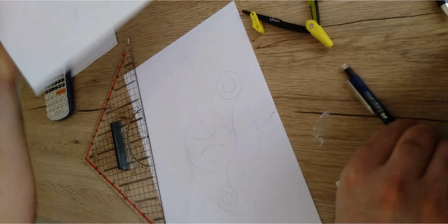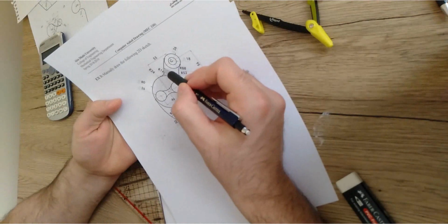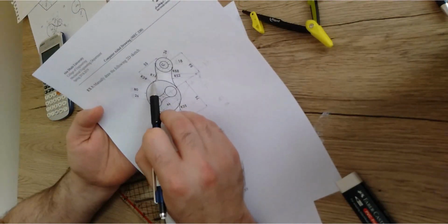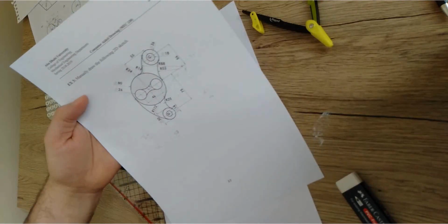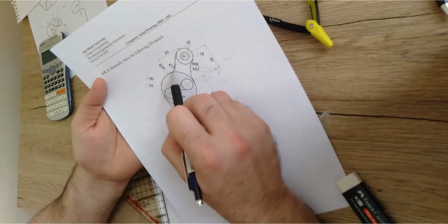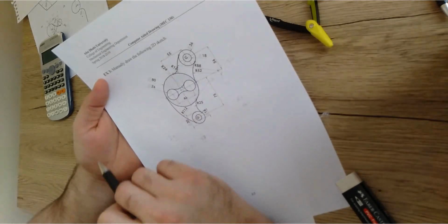The R16 now is tangent to this R88 and this big circle. At these two points, this is the first tangent point, this is the second tangent point. Make sense? So what does this mean? If I ask you where the center point of the R16 should be, it is going to be a little bit up here.